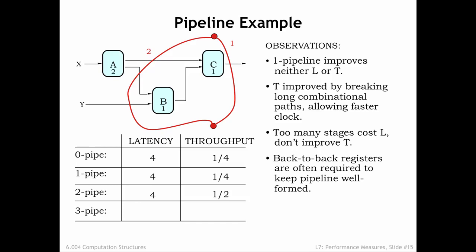This creates a 2-pipeline with a clock period of 2, and hence a throughput of 1/2, or double that of the 1-pipeline. We can add additional contours, but note that the 2-pipeline had the smallest possible clock period, so after that, additional contours add stages and hence increase the system's latency without increasing its throughput. Not illegal, just not a worthwhile investment in hardware.